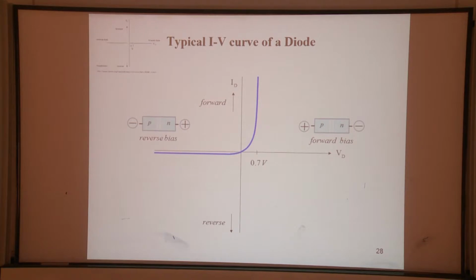At the reverse bias, there are currents, but this current is not big. So sometimes we regard it as open circuit because current is very low. And it is not dependent on the reverse bias anymore. And it's negative current. Actually, the negative and positive is defined by human. You can define the positive or negative in either way. But in this case, I define the diffusion current as a positive direction of the current. So the drift current will be negative.